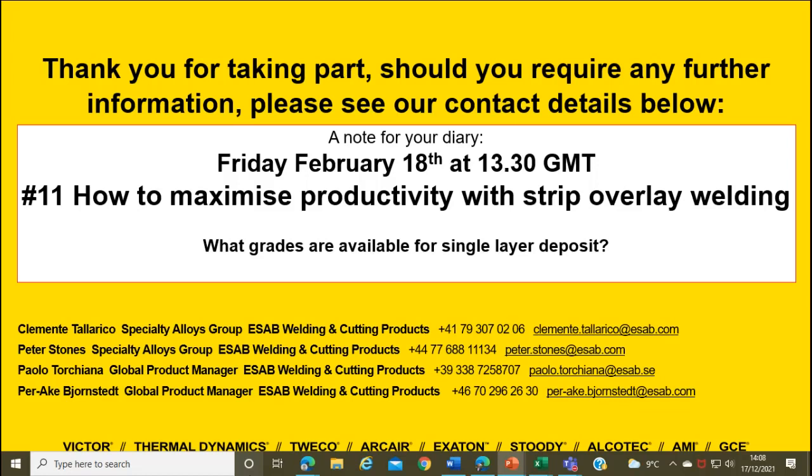I would add also something else. First of all, it is clear that it should be brought in relation to how much energy you bring in. That means that maybe for the overlay you go with a 30 millimeter strip rather than a 60, a smaller size of strip, and then consider as well, in regards to dilution, that I can only do a single layer with electroslag welding and not a double layer as in submerged welding. So that means that I extremely reduce the work and the heat that I bring into the material. Yes, exactly. Good questions.